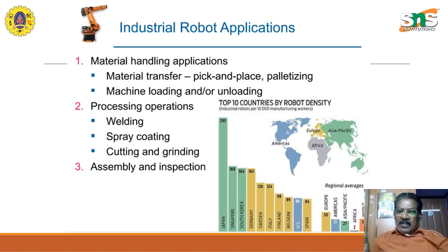If you are putting parts on a pallet, the robot knows the advancement to the next position. If it has put a part in place A, the next time it will not put it on place A again. It will put it on place B, C, D, like that, till the pallet is full. All these things get indexed by a small distance, and then it moves on.